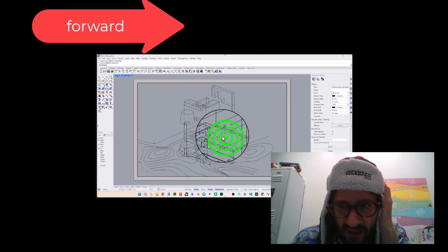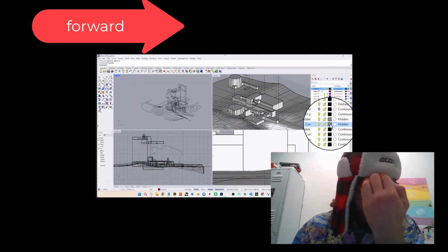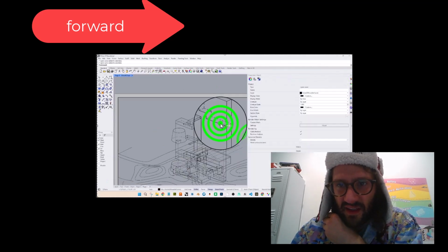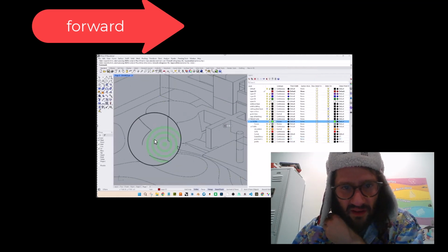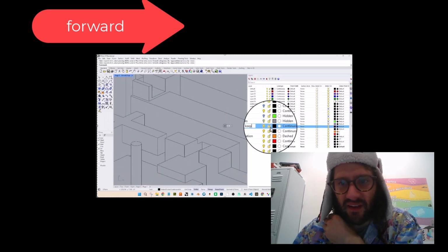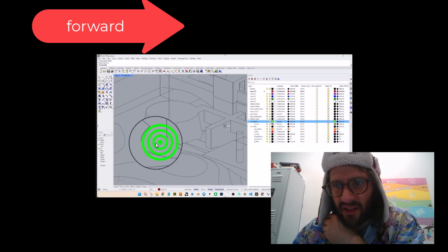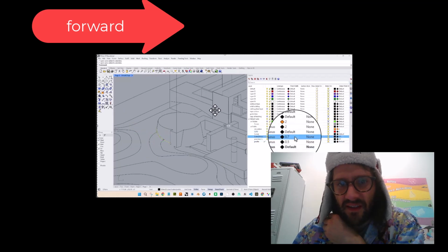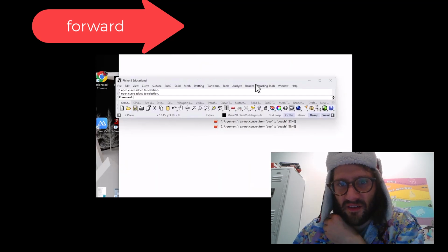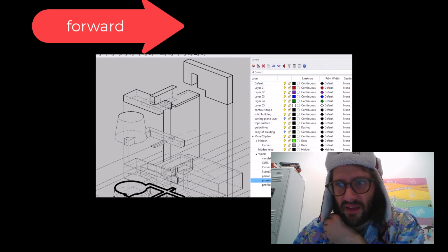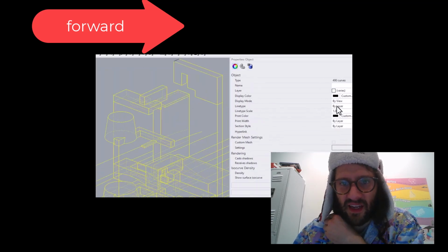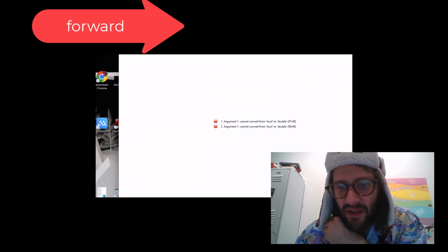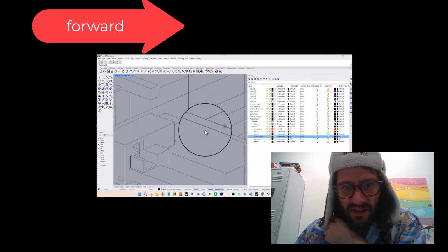and then I bring it into a layout space, and I start assigning layers and assigning line weights and the dashes. There was one thing that I had to do. I had to at one point select every line in the whole Make2D thing and go to the settings. I don't know exactly when I did it. I'm scrolling around, where I selected all the lines, and then in the settings I could even show you in here, right? If I select these lines, then I can go in, and the line type and print width, I just put to by layer. So that was important because it wasn't showing up.